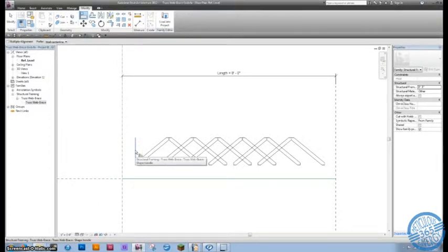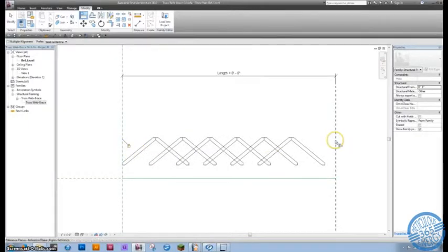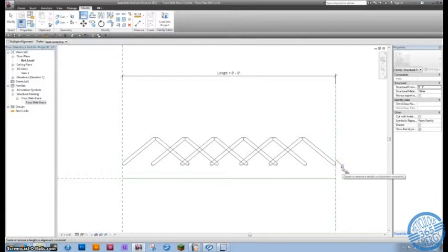The first highlight we get here is the shape handle. The second one would be reference, if there was one. The reference one is the one you would want if you have that functionality in your subcomponent. But if you don't, just go for the shape handle. Always go for references if you can. They provide better arrangement and attaching to reference planes.